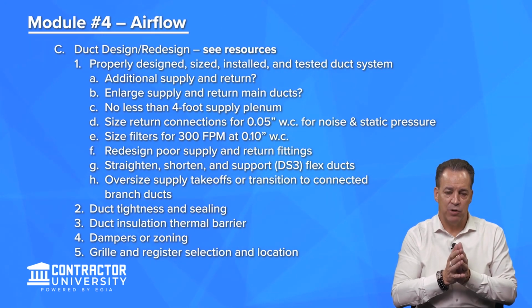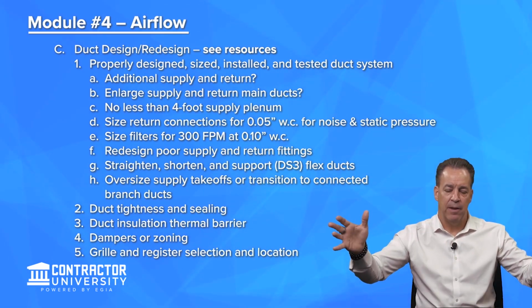But the idea behind a register is it's designed to throw the air. Okay, it's either throwing the air across the room from the sidewall, from the floor up and out, or from the ceiling, as a curtain is kind of coming out of the ceiling and kind of showering, if you will, over the people, without hopefully blowing onto the people.